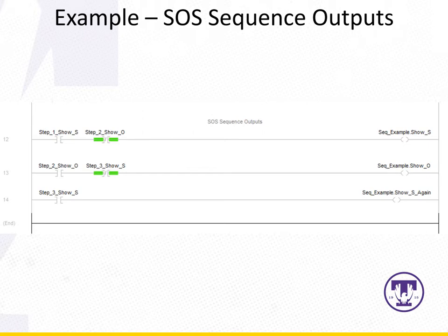So we have, exactly one more time, logical and consistent groupings, comments to divide those groups up, to separate those groups from each other, and to provide a description of what that group does, what the total impact of this group of rungs is. It provides the outputs for the sequence. Then we also have appropriate and helpful tag names. This is the requirement for this lab moving forward. Appropriate and helpful tag names, logical and consistent rung groupings, and rung comments to describe that rung grouping and separate it from other groups of rungs.